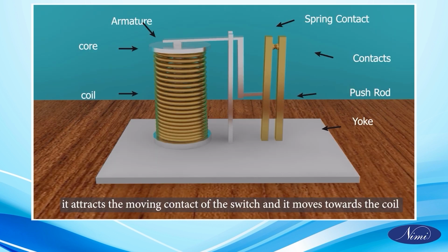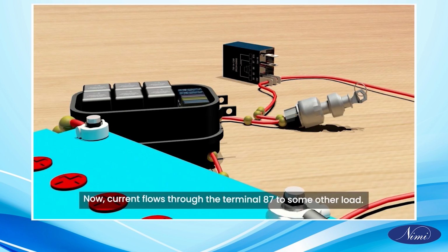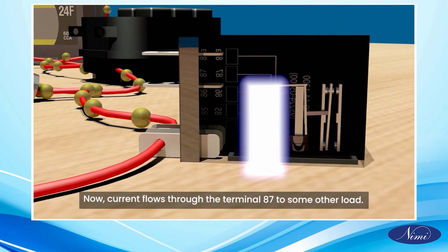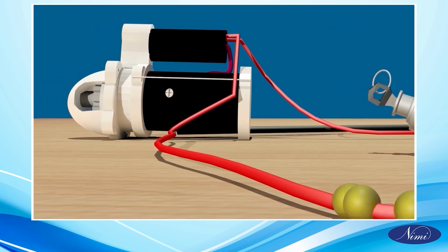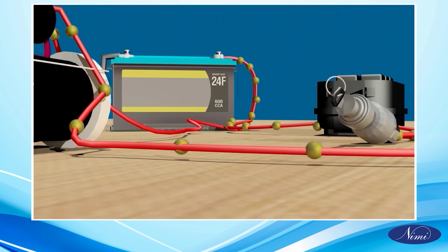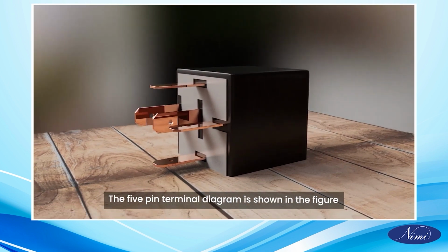It attracts the moving contact of the switch and it moves towards the coil. So, the terminal 87A disconnects and 87 connects. Now, current flows through the terminal 87 to some other load. The 5-pin terminal diagram is shown in the figure.